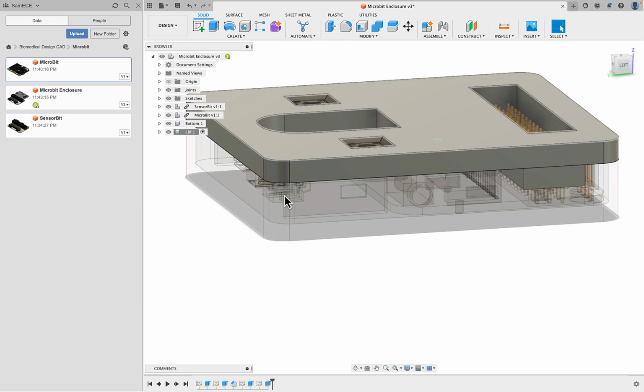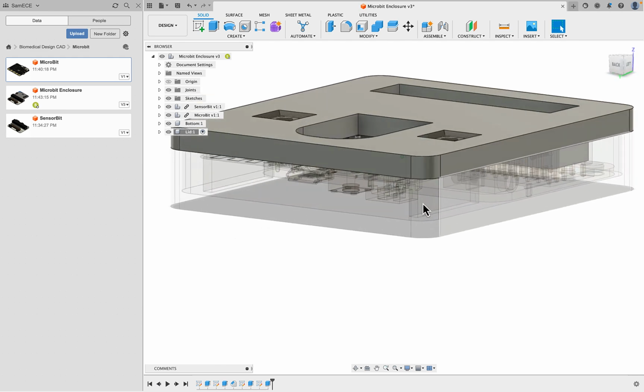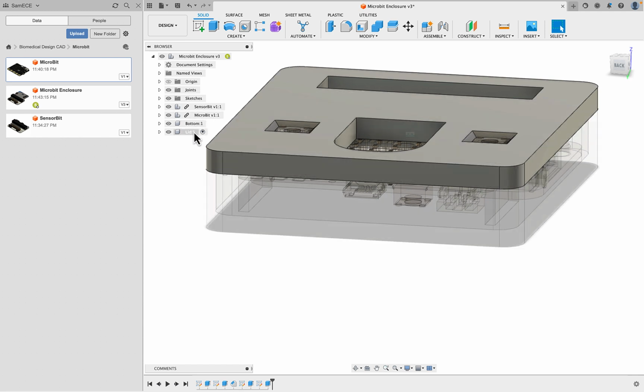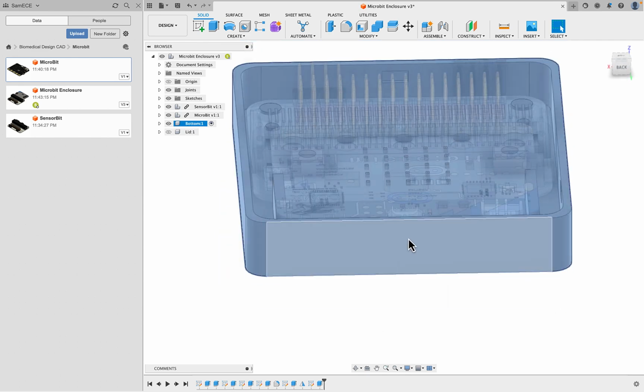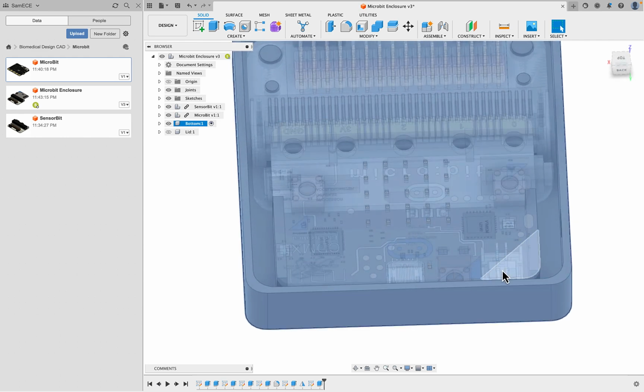So there's a USB micro plug at the end. There's also a white plug at the very end, and I don't know whether or not you'll need the sound, but there's a jack in the sensor bit, which we'll also like access to. So we just need a few holes in the sides of the bottom enclosure. So let's do that. So I'll switch to the bottom one, just hide the lid, and I'd like to do the cutouts for the white plug and the USB micro. So this one and this one at this edge.